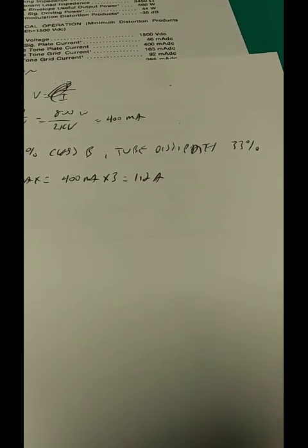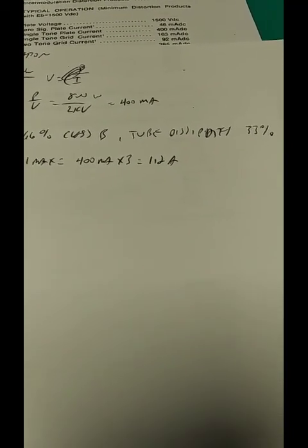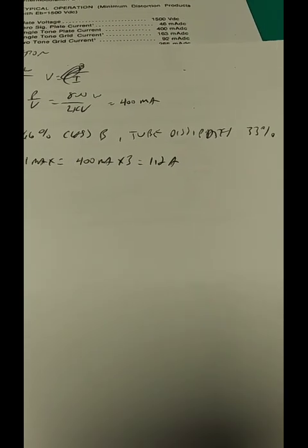The Care and Feeding document and my experiments with the Drakes show that the efficiency of a Class B amplifier is about 66% according to Eimac. In the Drake TR3 and TR4, it's about that. It's 3 tubes at a total of 52.5 watts dissipation. The wattmeter reading is 150. The accurately measured PEP and CW is 298. So you can calculate that out as the percent efficiency. That means the tube dissipates 33%. That's a third. So invert that, a third, times 3.